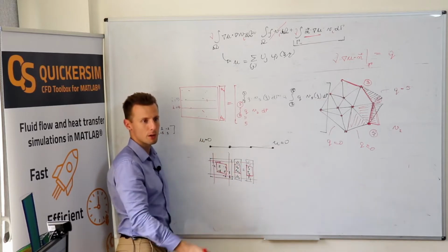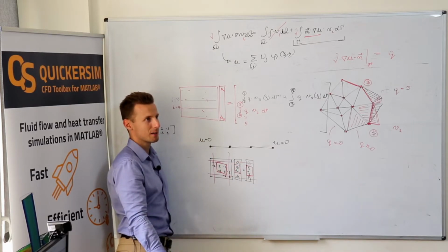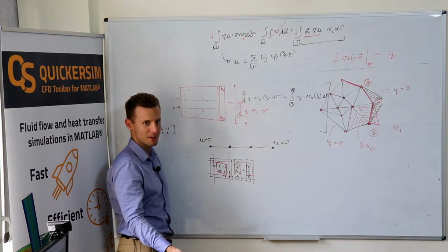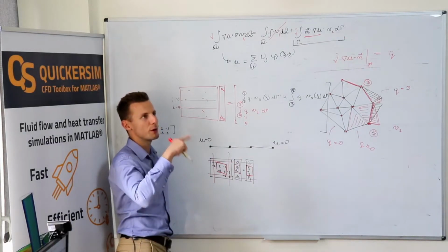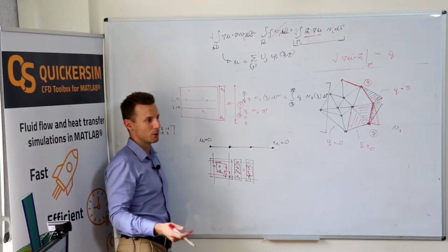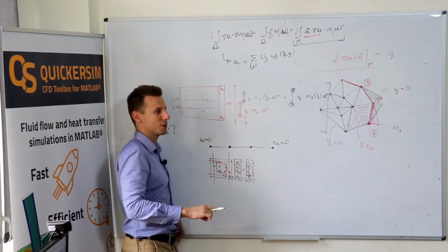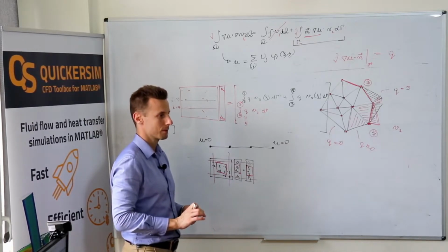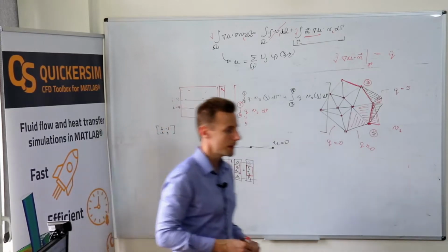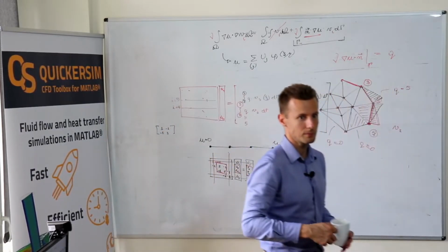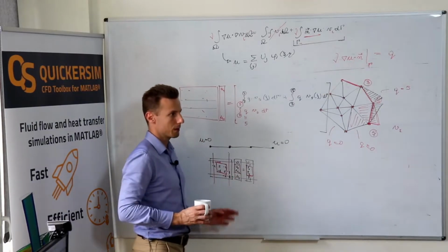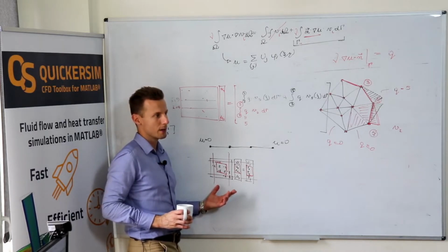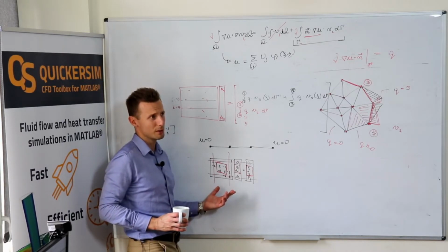You want to delete some boundary nodes, then it means that they are not ordered properly, they are not numbered properly. So you probably need to renumber your mesh. Then when you end up with the result, you need to renumber it back somehow. You just have to store the maps. Yes, you can, with a transformation matrix. Yes, you can. But it's not very convenient. You need to delete something from the matrix. You're building a smaller matrix. You've got some overhead to do it.